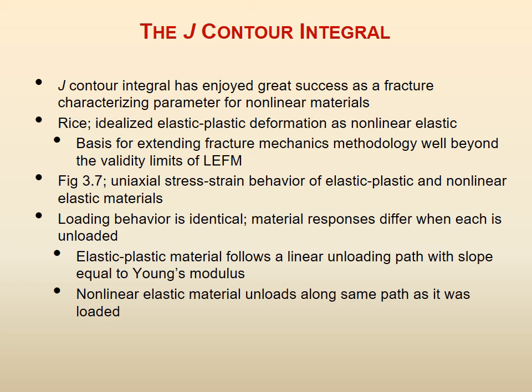K1 is the stress intensity in mode 1 and G is the energy release rate. Now in elastic plastic fracture mechanics, one quantity that describes it is the crack tip opening displacement, CTOD or delta, and the other is the J contour integral. So we have finished the introduction to CTOD, and now we are trying to cover the J contour integral.